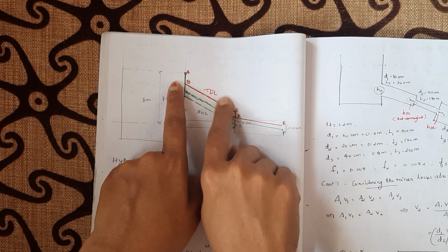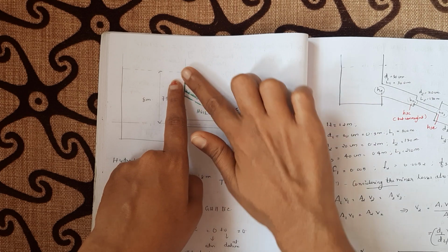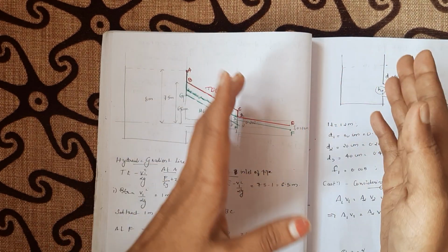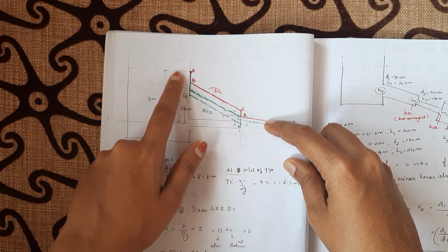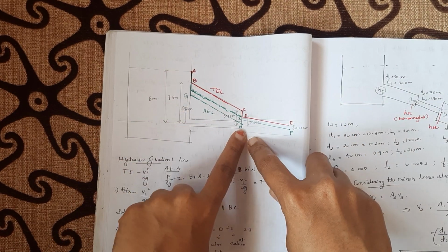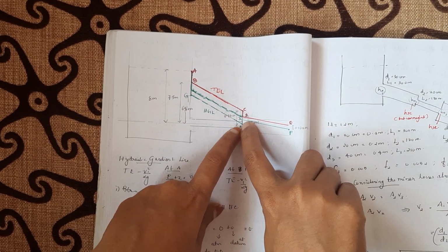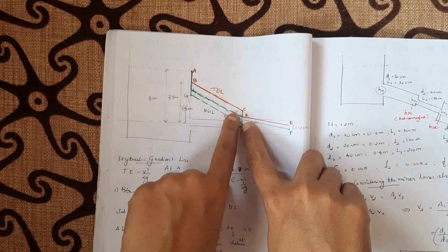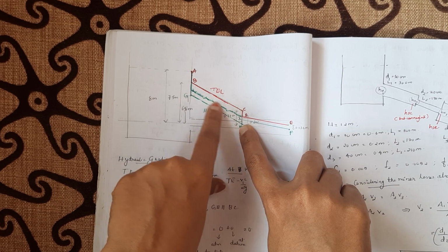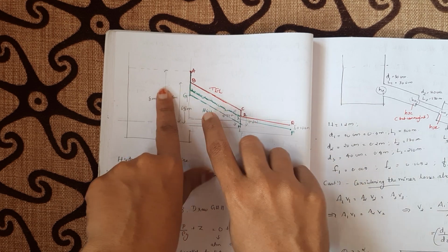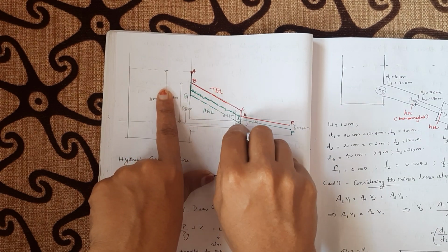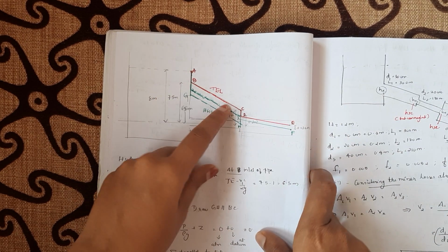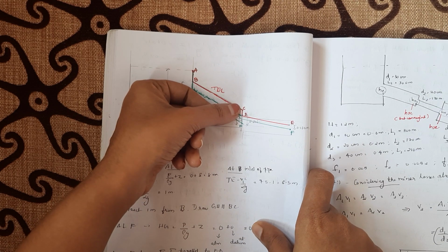There is a significant drop in total energy. That is why I have drawn a slanting line. This much frictional loss is there. I didn't mark the losses, I have just marked the total energy. So at this point, from the center line of the pipe, the energy will be 0.77 meter. I'm sorry for this line. This is wrong, I've marked it wrong. So just don't concentrate on this line. Just concentrate on this. This is our HGL. So up to the point C, it is 0.77 meter.